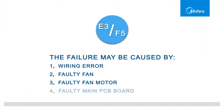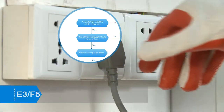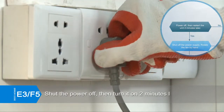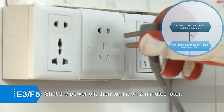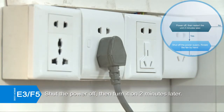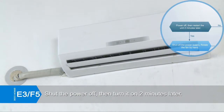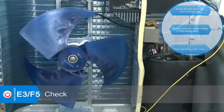The failure may be caused by: 1. Wiring error, 2. Faulty fan, 3. Faulty fan motor, 4. Faulty main PCB board. Shut the power off, then turn it on 2 minutes later. If the error still exists, shut the power off, then check the fan.